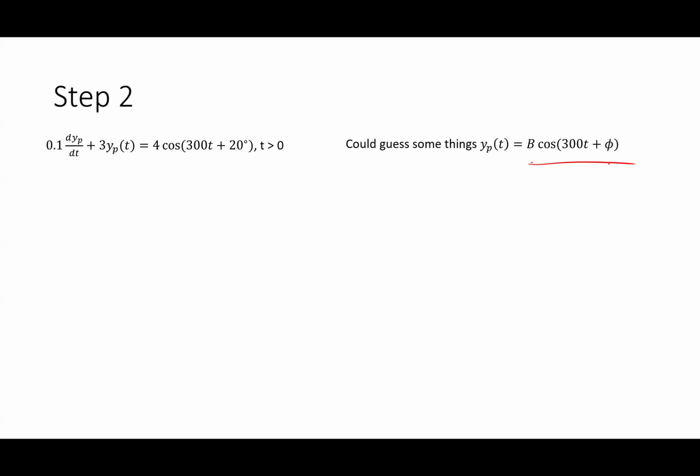One of the kind of magical things about circuits, not magical, it's any linear system, turns out: if I put a sine wave into a circuit, and the input to that circuit is omega, all the voltages and currents have that same frequency, right? The frequency never changes. The only thing that can happen in that circuit is the amplitudes and the phases phi are going to be different from the input.